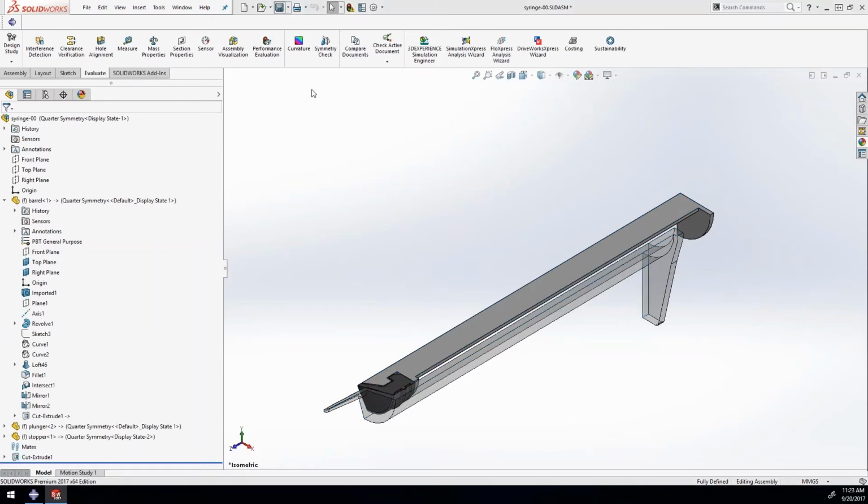And now that we do have it checked on, we've made all the changes that we want to make in SOLIDWORKS, at least for now. And so we can go through and push this over to Abaqus. When we have the associative interface turned on, it's just going to look like this little toolbar up here with this button. And like I said, all we need to do is click this button to push it over to Abaqus. We've got Abaqus running in the background, and we can click this here and push that over.